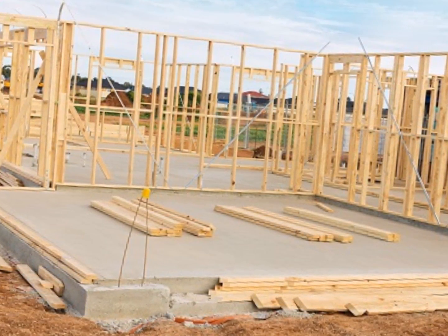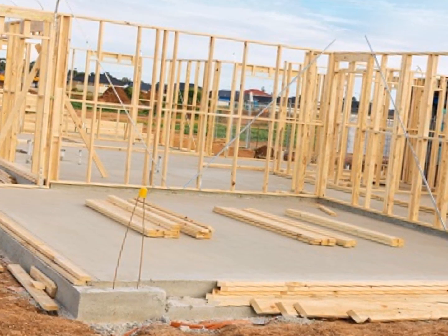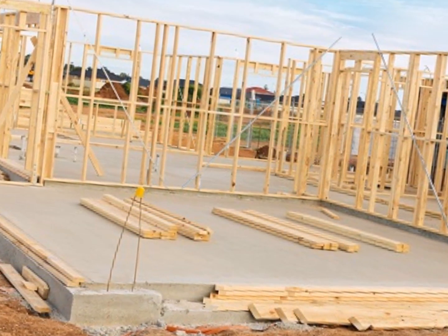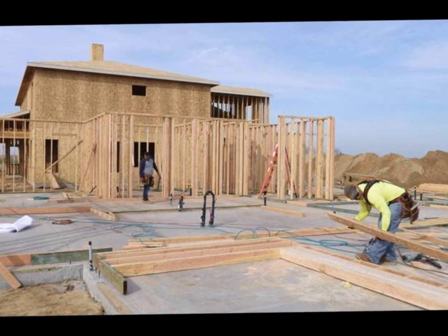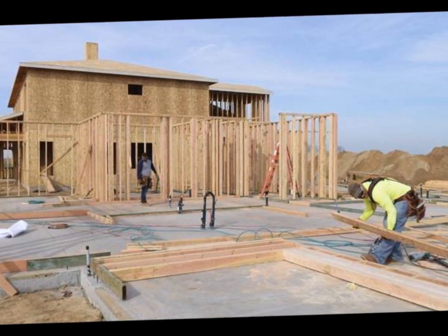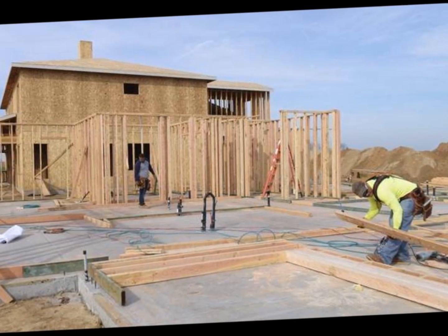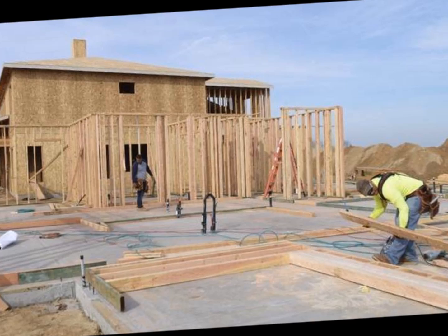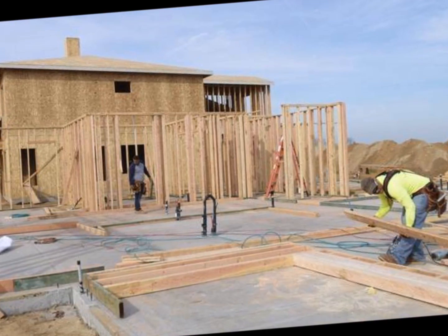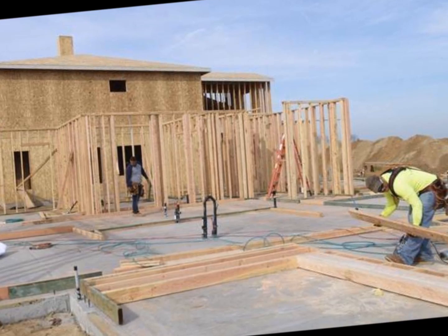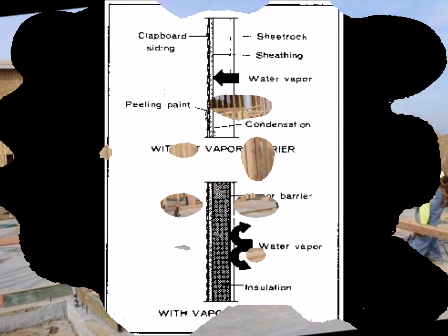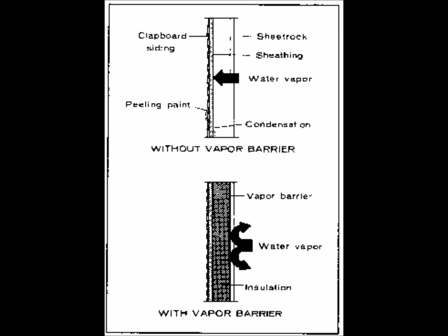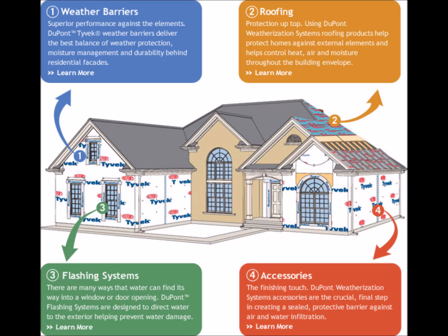During the construction process, most builders do not take time to cover their lumber or the framed homes, so they're really not protected from the elements. A wood frame home can absorb a great deal of moisture during the construction process. For example, wood fiber saturation is easily 25 to 30% by weight. If you have naturally occurring wood rot and mold spores in the wood, they will activate when the moisture content rises above the 19 to 20% range. In order to prevent mold amplification, which is the accelerated deterioration of materials with mold growth, the moisture content must be kept below 16%.